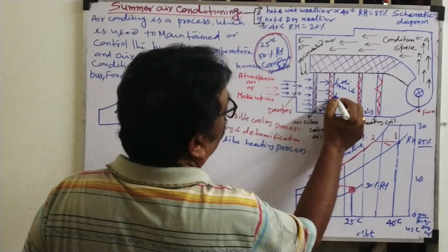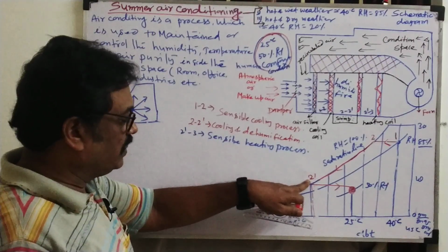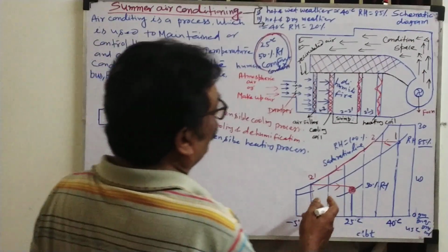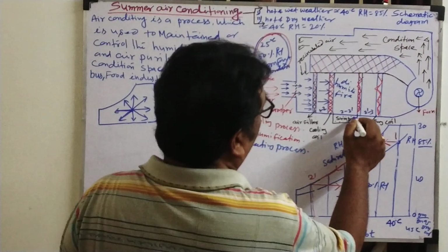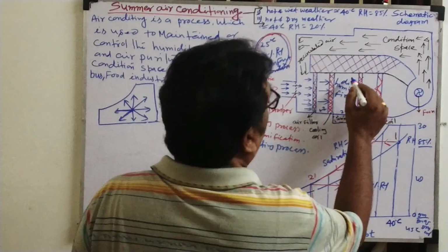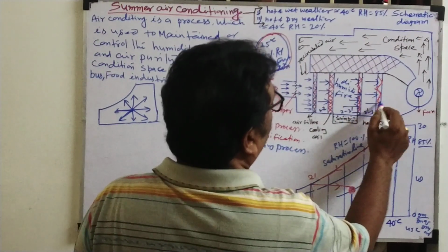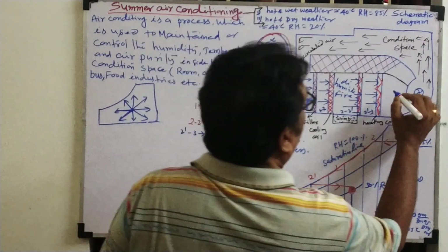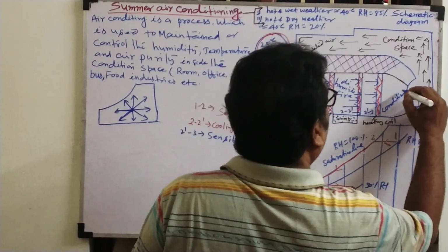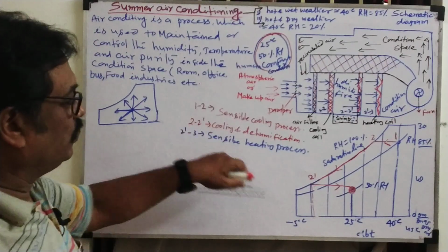This you can write dehumidifier. Okay, dehumidifier, what will happen? Moisture will still be 100%, but temperature reduces. Due to that, condensation will take place. Due to this, some water particles will form. Those water particles will slowly accumulate in the sump below. Now this humid air passes through the heating coil and we get the conditioned air. Through the fan, it goes to the conditioned space. Okay, so this is the psychrometric design.